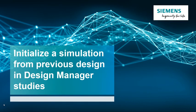Hi, in this video we will see how to run a design manager study where each design is initialized with the results from the previous design. This can be useful to allow each design to converge faster if the parameter being changed causes the solution to only change a little between each design.